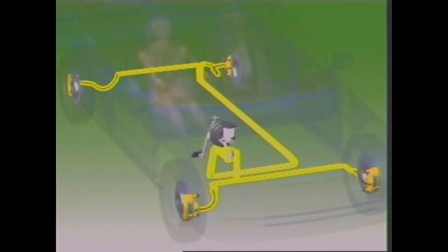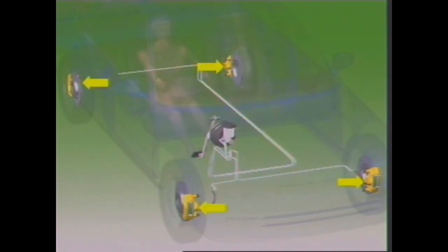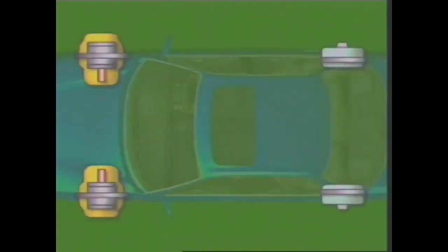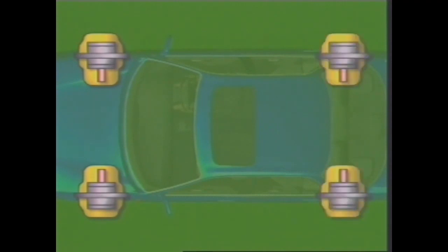The brake pedal operates a master cylinder. Hydraulic lines and hoses connect the master cylinder to brake cylinders at the wheels. Most modern light vehicles have either disc brakes on the front wheels and drum brakes on the rear, or disc brakes on all 4 wheels.